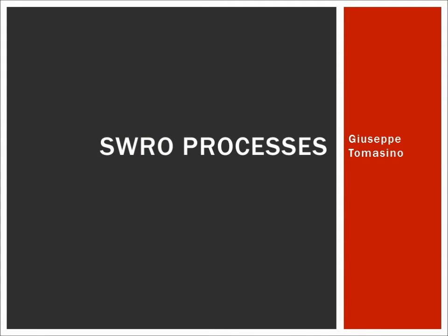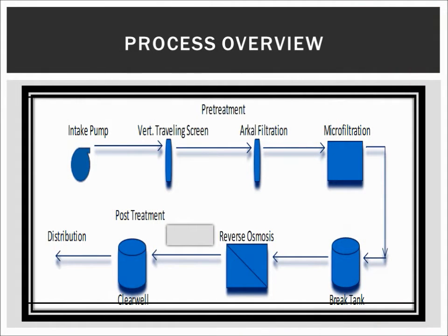The San Onofre Desal plant will treat open ocean intake seawater to produce potable water for human consumption. This process will involve filtering suspended solids and removing dissolved solids and bacteria in the water. Due to the difficulty in removing dissolved solids such as salts, a reverse osmosis process, or RO process, will need to be utilized. However, in order to prepare the water for reverse osmosis treatment, a few steps will need to be taken before passing through the RO membranes.